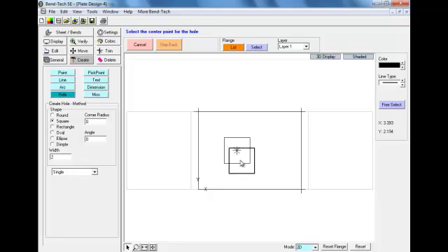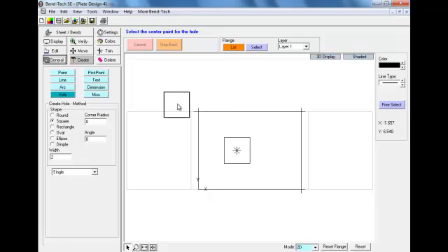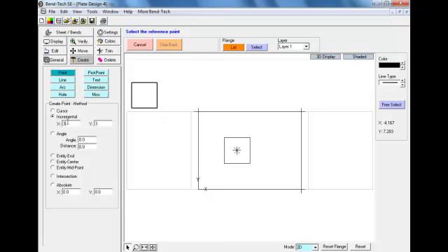We're going to use a square hole in this case with a 2-inch width. Selecting our last point we created, we can now place that hole. We're also going to create a cutout in this flange. For this, we need to select a couple points for that cutout.